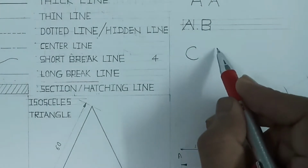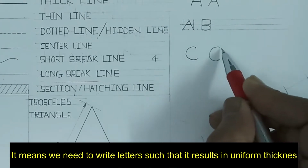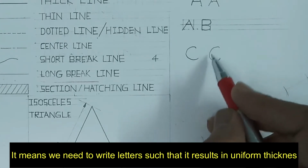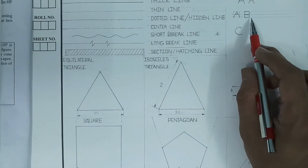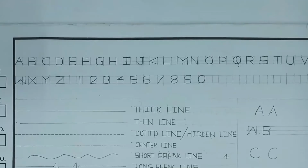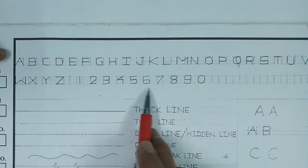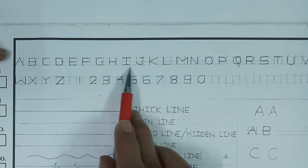Single stroke means that with only one stroke, if we draw a particular letter, then the thickness of the line becomes uniform. There should not be unnecessary variation in the thickness of the line or the letters. That's why we call them single stroke letters. Generally letters are specified by the height with which we draw them. Here I have drawn all these letters from A up to Z, and all these numerals from 1 to 9 and then 0. So every letter is specified by a certain height.